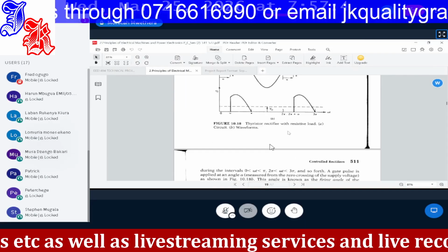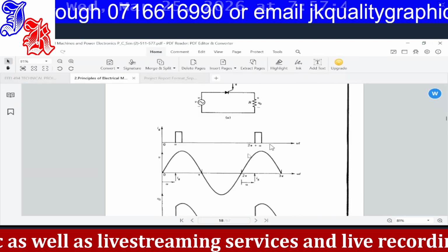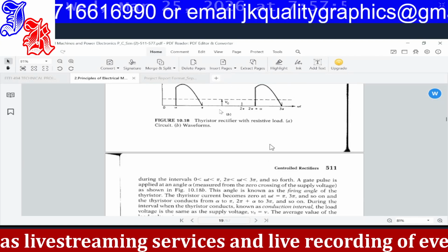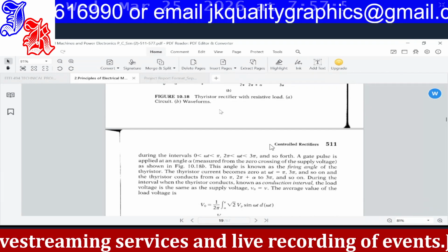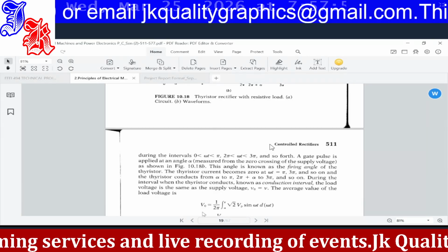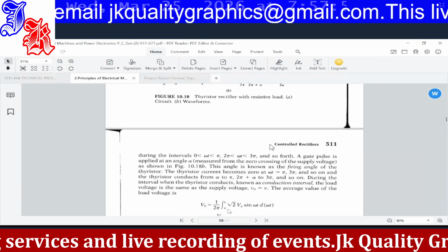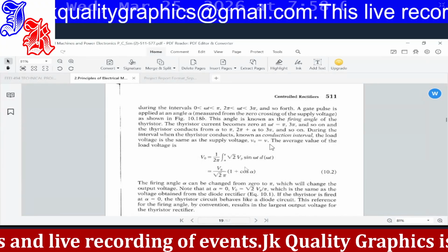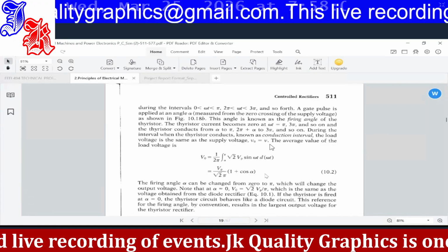And then, yeah, that is the diode. But then we can have a thyristor. And now with a thyristor, we are not just igniting from 0. It is the same operation, but now we are not igniting from 0. We are igniting at our chosen point. It can be any point. Now we give it alpha instead of 0. And so for this one, the result will be 1 plus cos alpha.